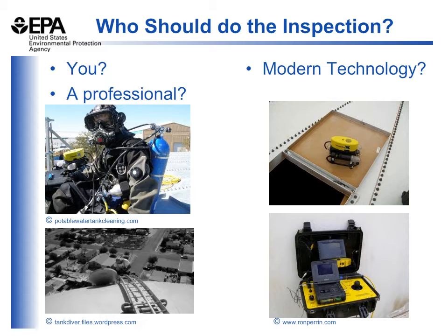If you have ground level reservoirs, your annual and periodic inspections may be within the capabilities of your staff, so you wouldn't necessarily need to hire a professional. Or if your water reservoir or tank is emptied for interior inspection, you would want to consider using someone who has confined space training or other special safety training. If you're sending workers in the tank, you want to make sure that there's adequate ventilation and adequate air quality for them to breathe properly. You also want to provide security and fall protection for the ladders and make sure there's sufficient lighting.